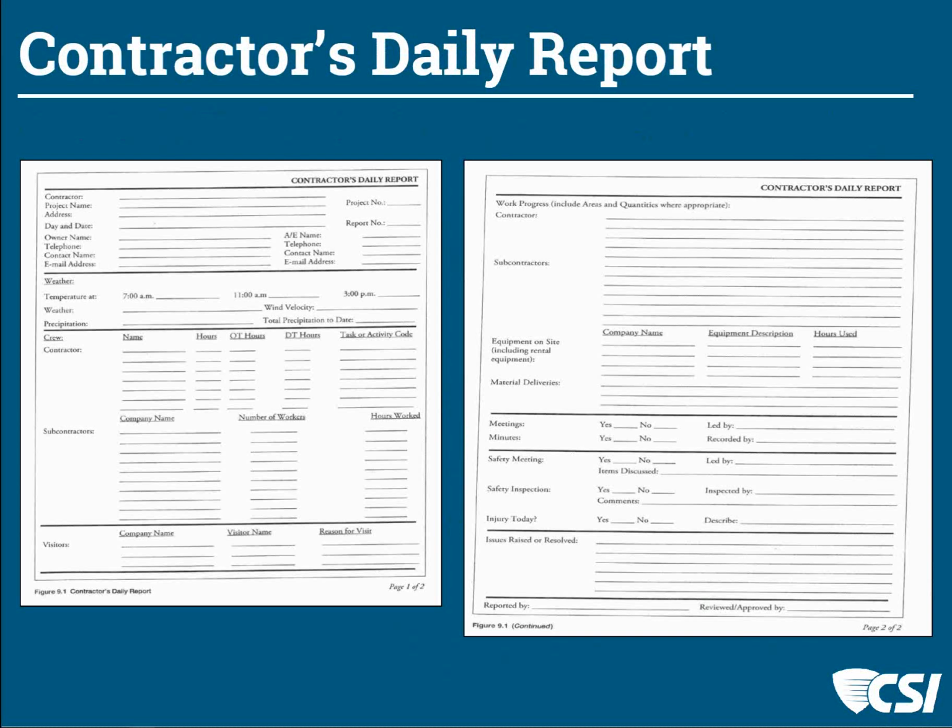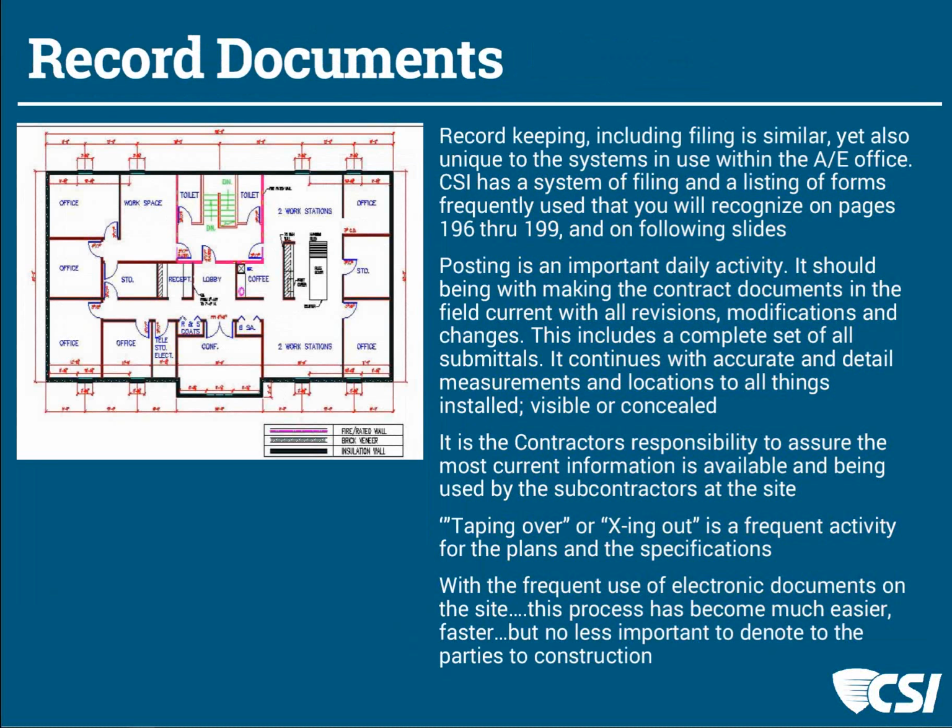And along with those reports, if we go to the next slide, one of the things that we also want to see them doing is keeping up with record drawings or record documents. So they're marking up what's been moved, where it is now. This also is something that's got to be happening on a daily basis. You can't wait till Friday to come up with this and try to remember.